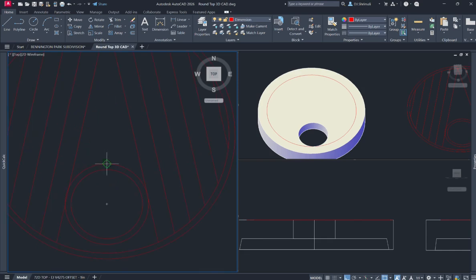So now we are creating the horizontal rebars. Okay, so I'm using the same command, TR enter. If I press shift along with it inside the command, it will extend the rebar. And then I'm using the offset command to offset the rebars. Here it's 6 inches, but it depends on the engineering design. And I'm using the trim and extend command here.